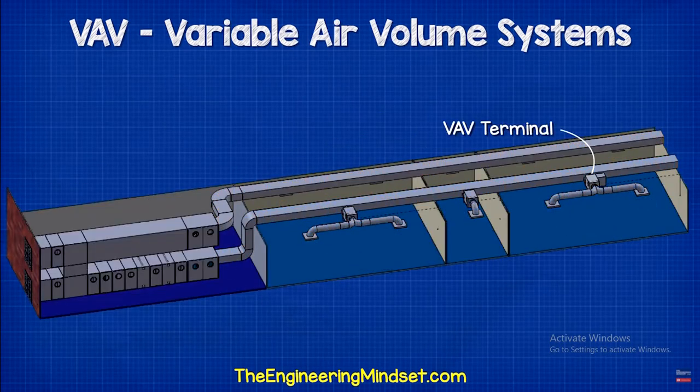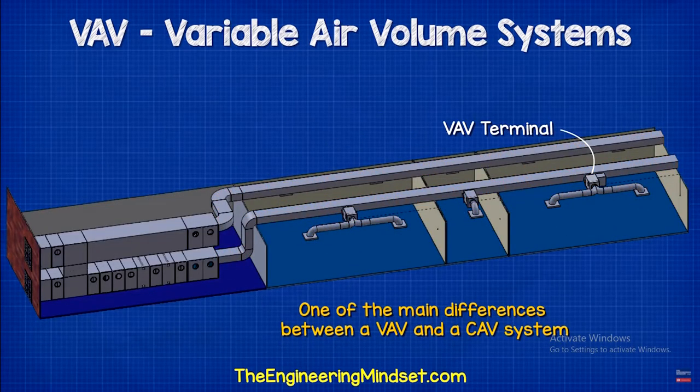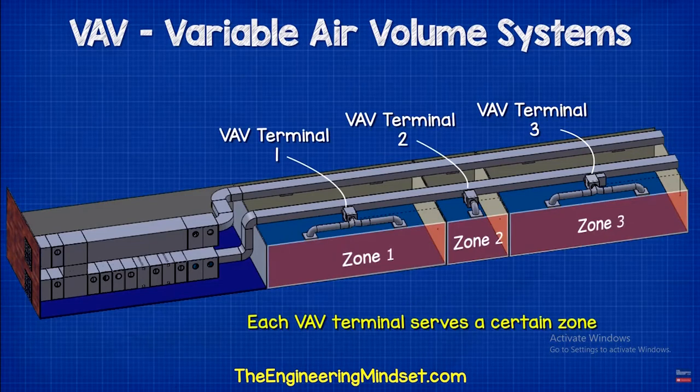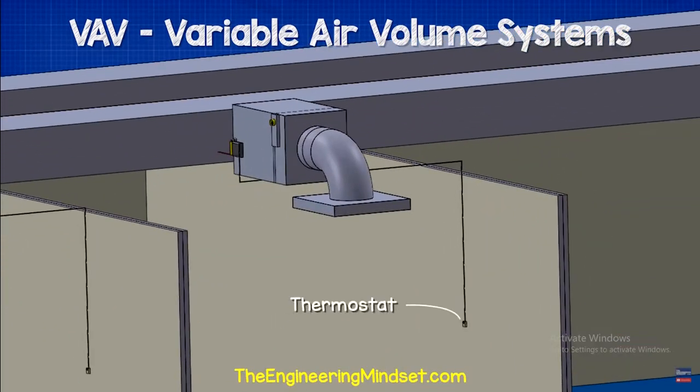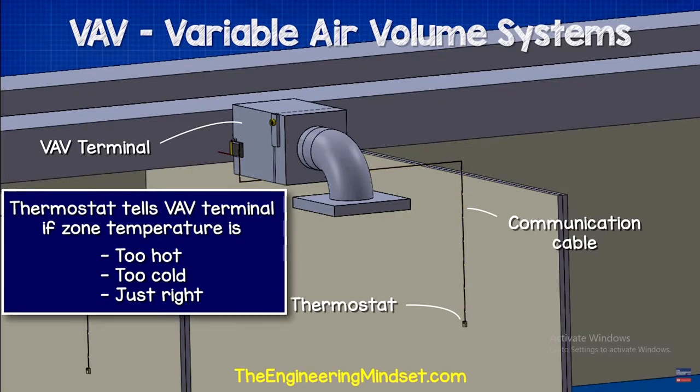There's nothing too complex happening inside these. On the side we usually find a controller, which is mounted onto the actuator. The actuator controls and rotates the shaft. Connected to the shaft is a damper. The damper is basically a sheet of metal. The damper can modulate its position to cover or uncover the inlet.